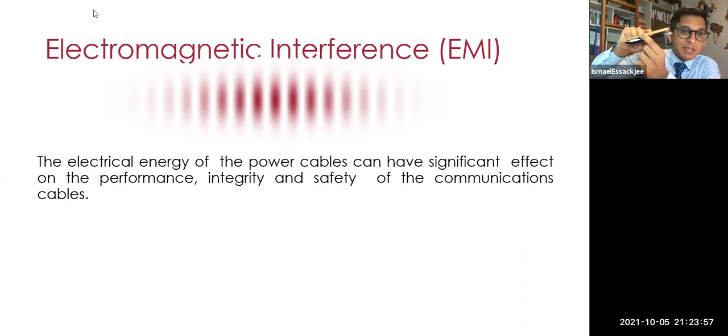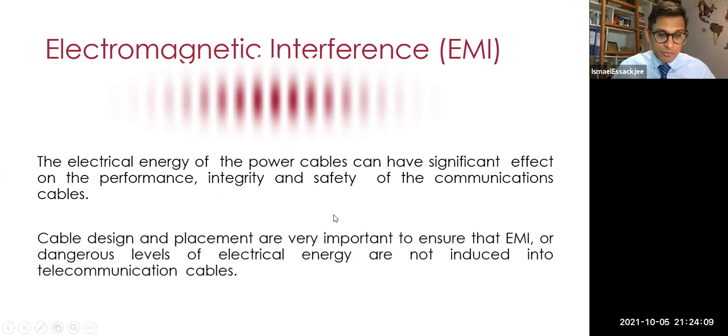The power cable has been designed to sustain the heat, the insulation that you have on it has been designed to sustain the heat, but the communication cable has not been designed for that. So it can cause safety issues. It can burn or it can damage your communication cables. Cable design and placement are very important to ensure that EMI, electromagnetic interference, or dangerous levels of electrical energy are not induced into telecommunication cables.